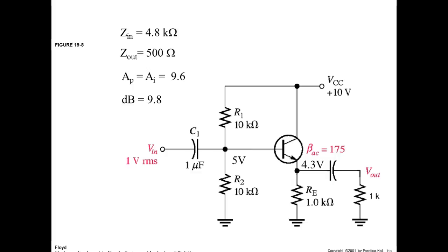The first amplifier, we want it to have high input impedance, because then as we go through, we're going to start lowering the impedance, right? You understand that? And eventually, we're going to usually drive a low impedance load, and that's where we're going to use this common collector to drive those speakers, to drive those solenoids, to drive those very low impedance circuits or low resistance circuits.